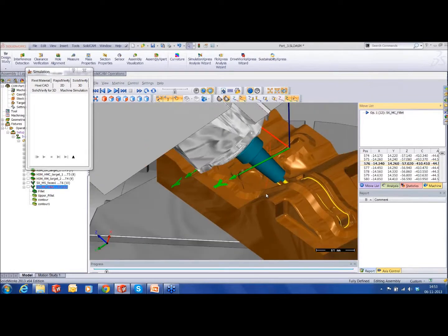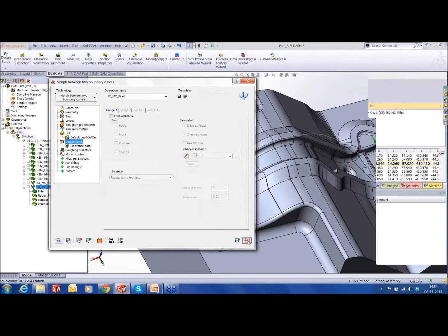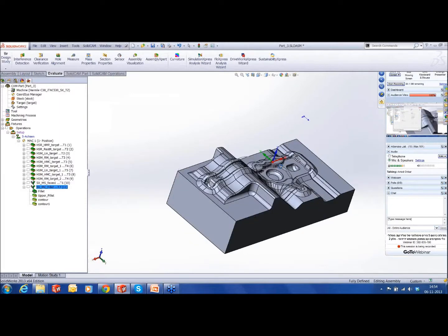And the greatest benefit here is it allows you to use the shortest possible tool to cut a portion of the part, or you can use it to cut the entire part, again by defining several zones of cutting. So these are the two nice examples that I could give you in explaining simultaneous 5-axis for cutting die mold parts, especially for finishing areas where you feel that small diameter tools with longer length could cause problems. Right.